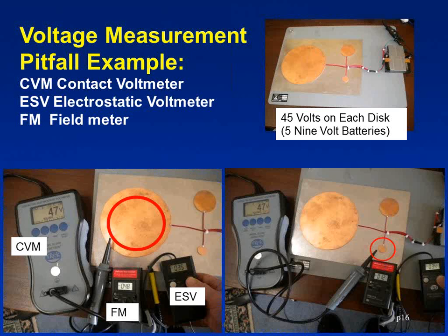So that's consistent. Carl, I know if you look closely, you'll see there's a low battery light on, and that's why the electrostatic voltmeter is off. Oh, okay. That makes sense. We need to fix that slide. But it would normally be the 47 volts that you know throughout all 3 measurements.